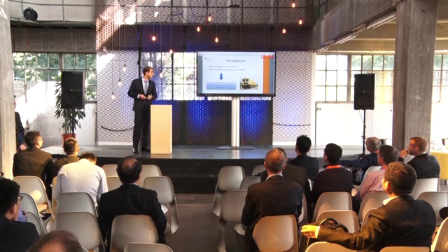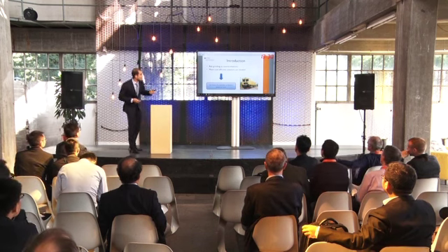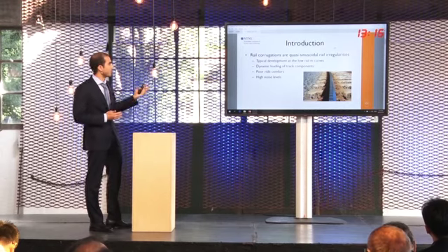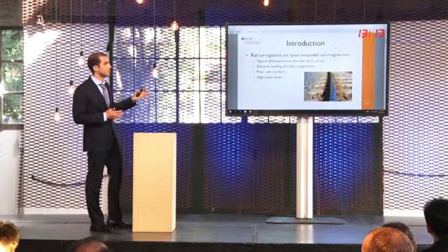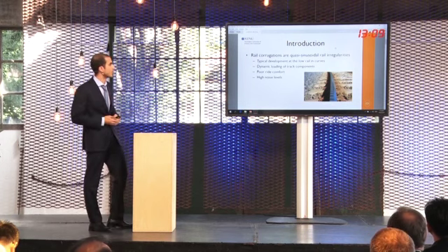Yeah, all right. Here, just to give a bit of introduction, you know everything about it, I'm sure. But rail corrugations are quasi-sinusoidal rail irregularities. There are a lot of types of rail irregularities, and one of the most common ones typically develops on low rails in tight curves, which is the so-called roaring corrugation.